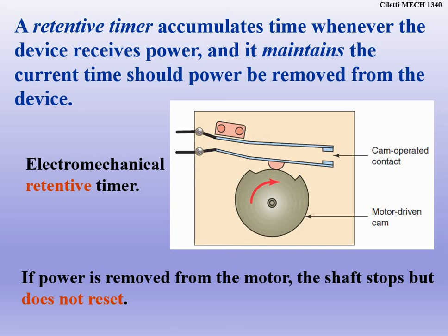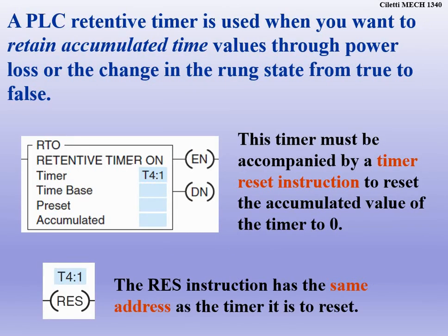Why do we do it that way? Well, if something does happen, we don't have to drain the entire tank and start over either. So that's really what's going on when we want to use a retentive timer. It accumulates the time, keeps track of the accumulated time and stores it. So if something gets removed, you're going to see, when we do the retentive timer, I'm going to toggle the switch on and off a bunch of times, and you'll see it'll still keep track of how far into its time it is before it goes forward. Then you can still have retentive on delay and off delay for a retentive timer. We're just storing its accumulation data.